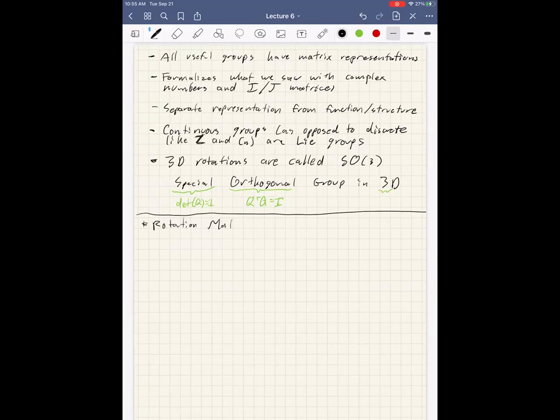Rotation matrix. I'm going to dig into this rotation matrix stuff a little bit more. It is group theory, but we're going to do it in a more intuitive way. So the question here is, if I have a gyro that gives me omega of t, my measured angular rate, and I know my initial attitude Q naught at t0, and I have a gyro strapped onto my thing and I'm moving around, how do I integrate the gyro?